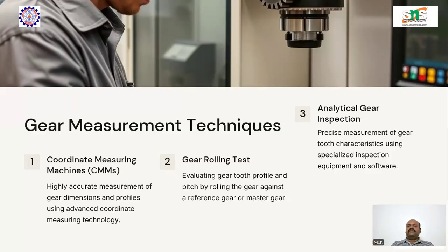We take the gear profile of the object to be measured with the help of a touch probe with sensors. So we get the profile of the component using a probe, and we coordinate the same with the measuring machine that converts this into an image, and from the image we can confirm the different dimensions mentioned in the drawing.